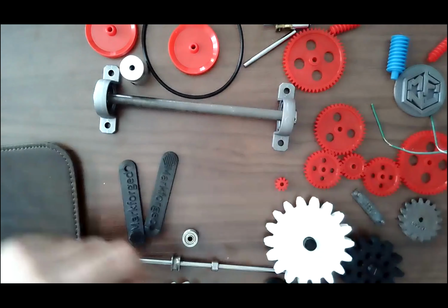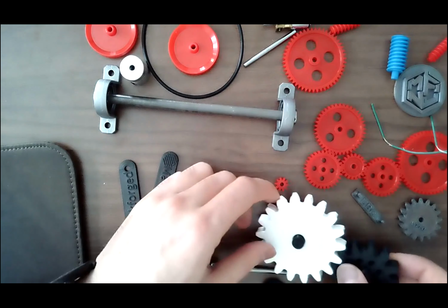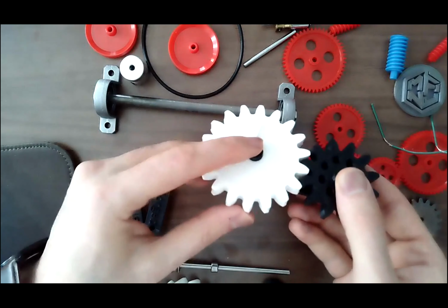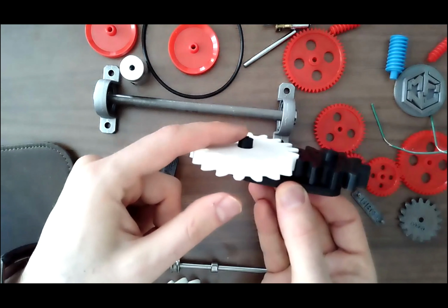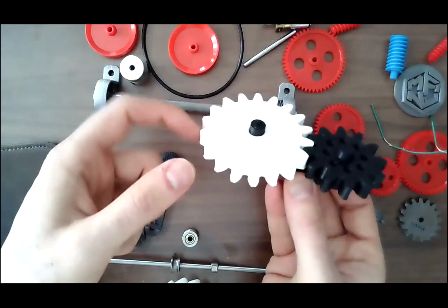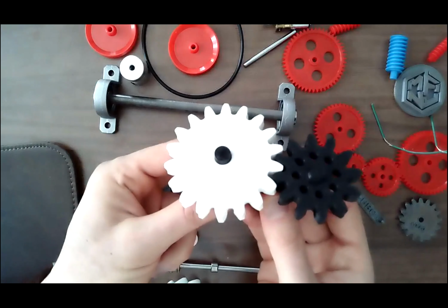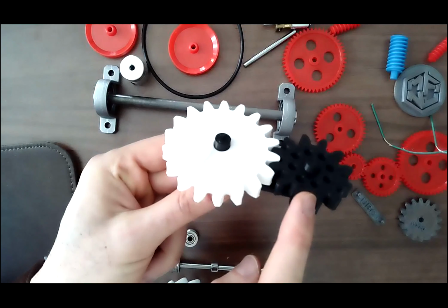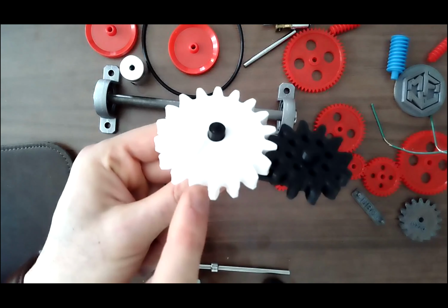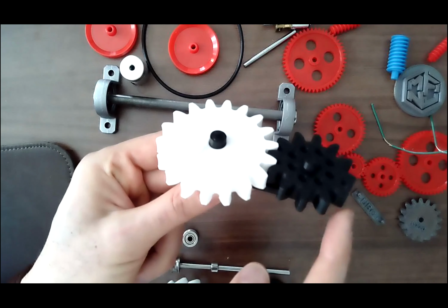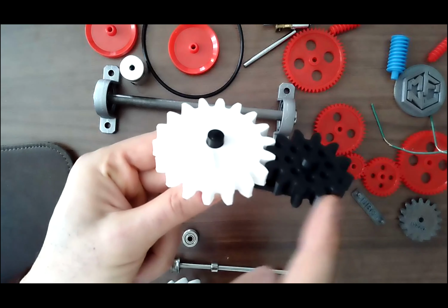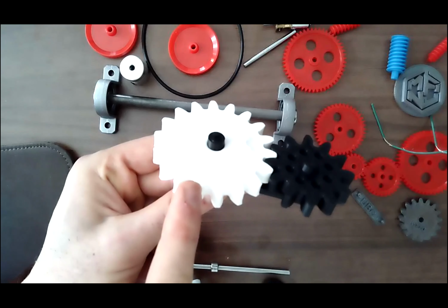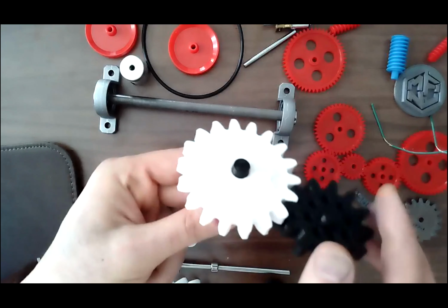But for now, we simply say that we have two gears, one on each shaft, like the one that I'm showing you. And if I rotate one, the other one is going to rotate. So I can have a small gear and a big gear. The small gear, usually we call it a pinion, and the larger one, we call it a gear. So if I go from small to large, the speed decreases, but the torque increases. Or it can be the opposite.